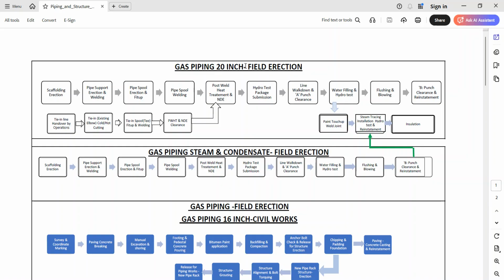in your schedule. Once you do the water filling and hydro test, there will be a pressure gauge set up in your manifold. Manifold is basically some kind of water from the tank. It will go through this manifold, and it will be routed to your piping system. Okay, so the pressure gauge will be fitted one in the lower position and another in the higher position. Then once the pressure is witnessed, they perform this hydro test for a particular duration.